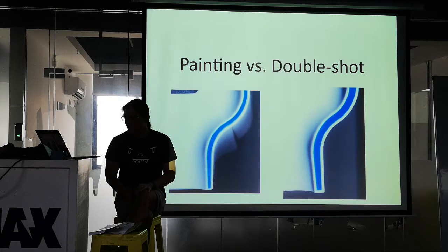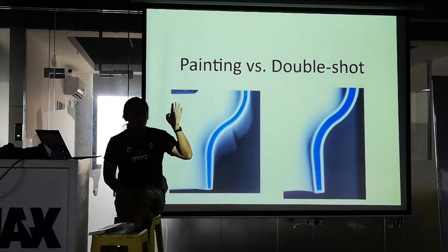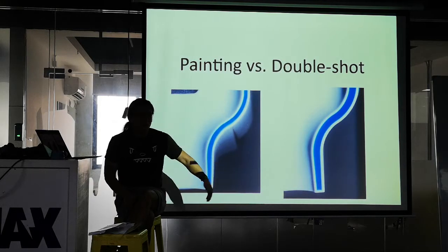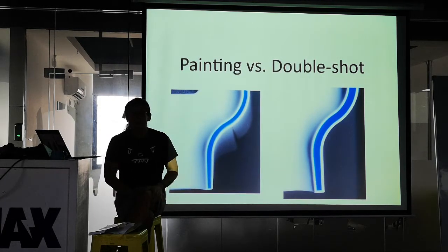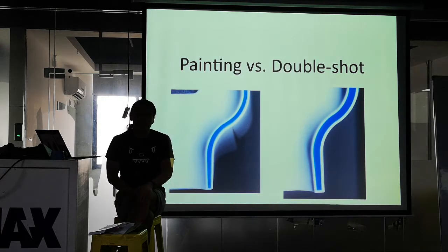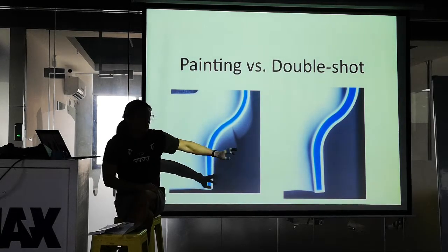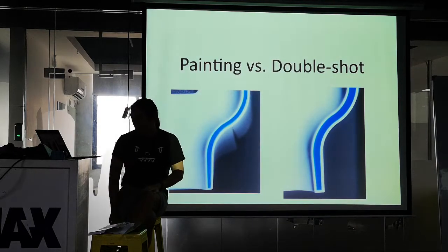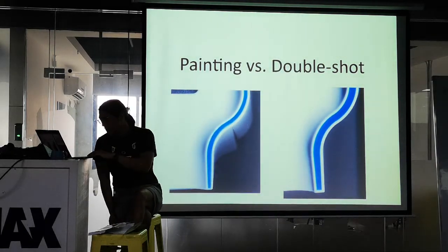And then someone was like, why don't you use a double shot mold? So we first shoot white, and then we shoot blue in the mold, and it's going to be injection molded. It's going to be perfect every single time. I was like, that's the thing. And then they went ahead and we paid for the tooling to do that. It was expensive, but we're throwing away $1 a unit every single time, basically. The double shot tool got this perfect blue line every single time, just right, for a little bit of extra cost.